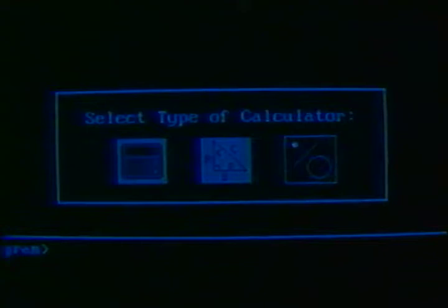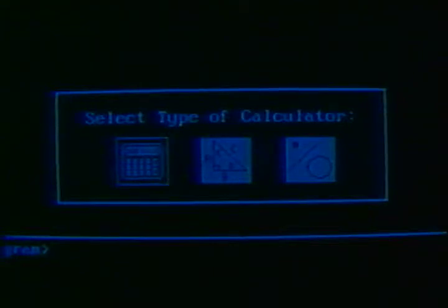The third one is a geometry calculator for inputting points, lines, and circles, and for finding tough-to-define tangency points and intersections, much like a built-in CAD/CAM system. All 3 calculators have store and recall functions, so that any XY coordinate found can be inserted directly into the CNC program that is being worked on. Not only is programming time and effort saved, but many potential keystroke errors are completely eliminated. We'll start with the math and trig calculator.